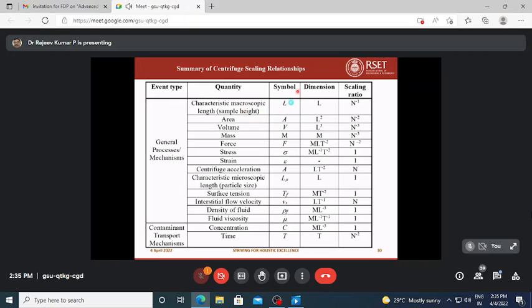This is the kind of beauty of the geotechnical centrifuge. You can simulate such prototype conditions in the centrifuge. You can even time contaminant transport. Time can be modeled, so within a few seconds you can get maybe 1 year or even 2 years of traveling time of a contaminant in the field.